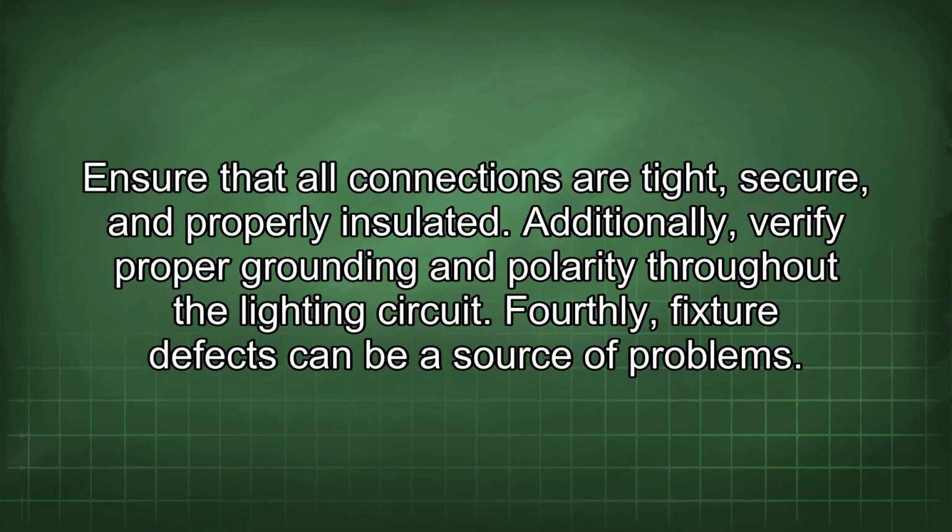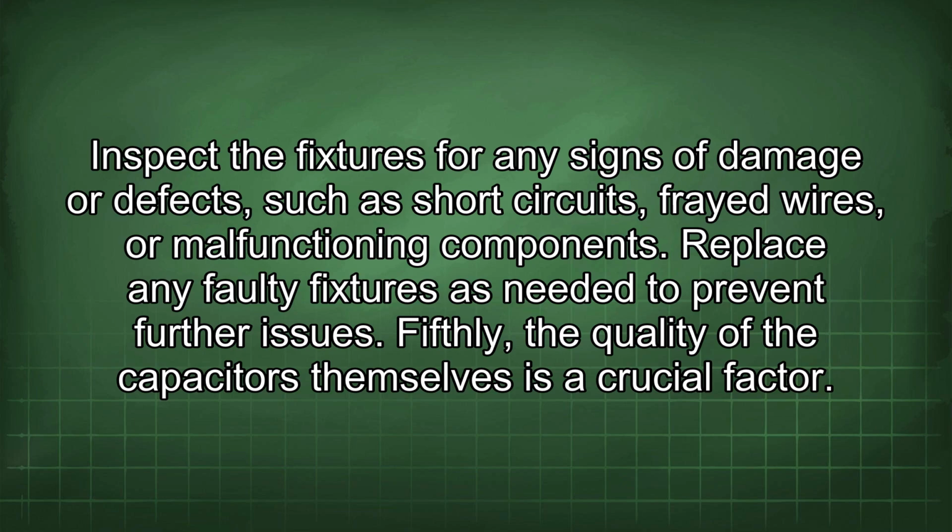Fourthly, fixture defects can be a source of problems. Inspect the fixtures for any signs of damage or defects such as short circuits, frayed wires, or malfunctioning components. Replace any faulty fixtures as needed to prevent further issues.